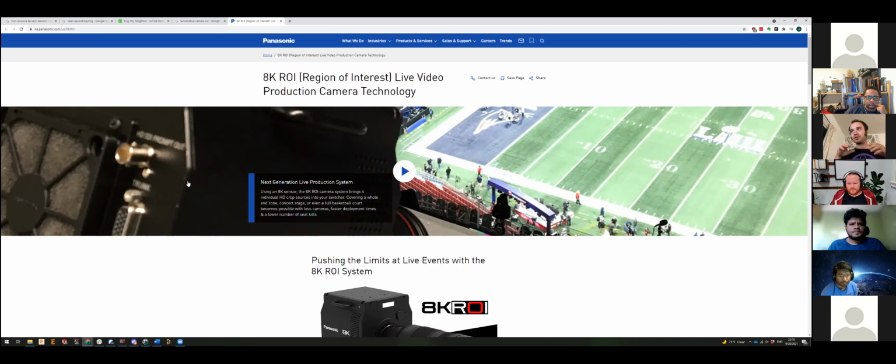So you want to read out the entire frame, maybe once every 1/15th of a second, and then you want to check out stuff that's interesting at a higher frame rate, maybe 60 or 90 frames per second. You can achieve this with sensors that allow you to say, I only want you to read out this section of the die and put it in a buffer, and do that at two different sample rates. This allows you to do this kind of dynamic checking out of what's going on.